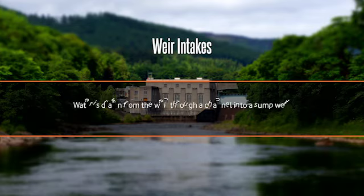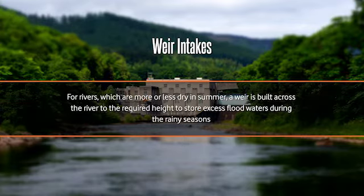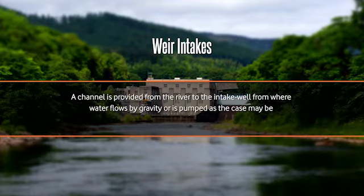Weir intake. Water is drawn from the weir through a channel into a sump well. For rivers which are more or less dry in summer, a weir is built across the river to the required height to store excess flood waters during the rainy seasons. A channel is provided from the river to the intake well, from where water flows by gravity or is pumped, as the case may be.